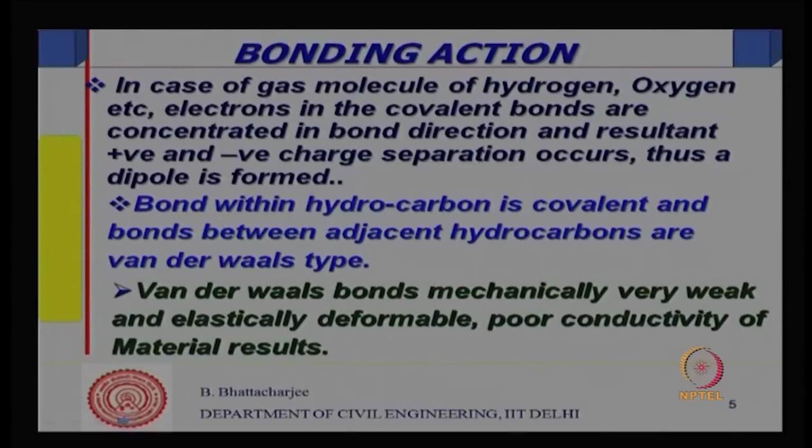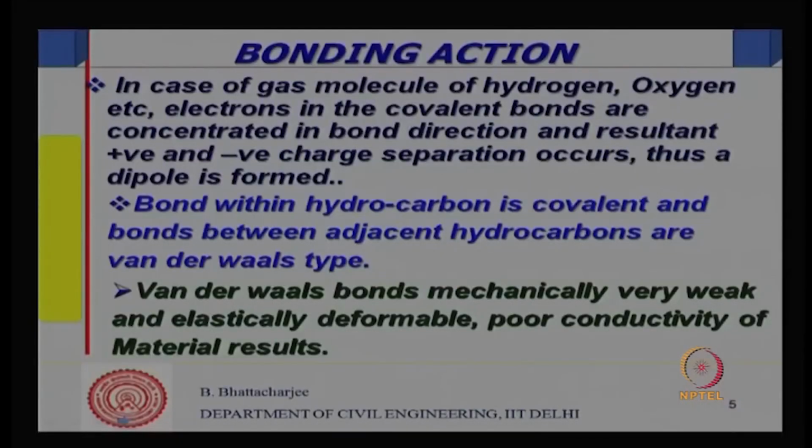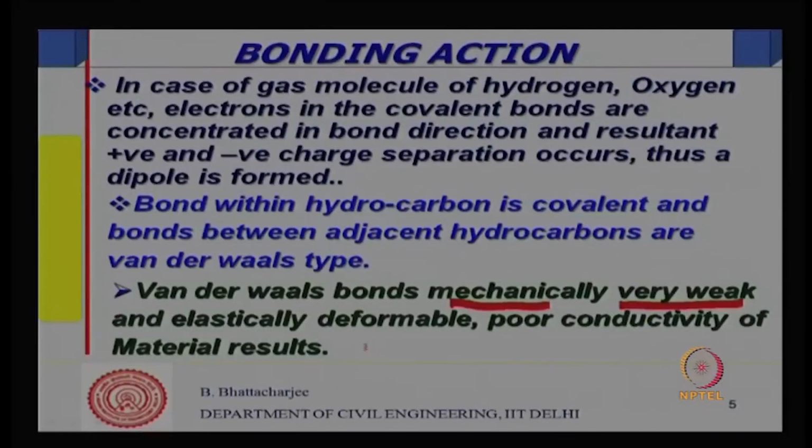So, CSH gel has this sort of bond, which is not a strong chemical bond but a van der Waals kind of bond, and gel to gel separation requires breaking those van der Waals bonds, right. Many other materials do not have any bond at all. For example, sand particles: between sand particles there are no forces of attraction holding them together, or stones. With a small surface area per unit mass or per unit volume, the forces do not act, right.